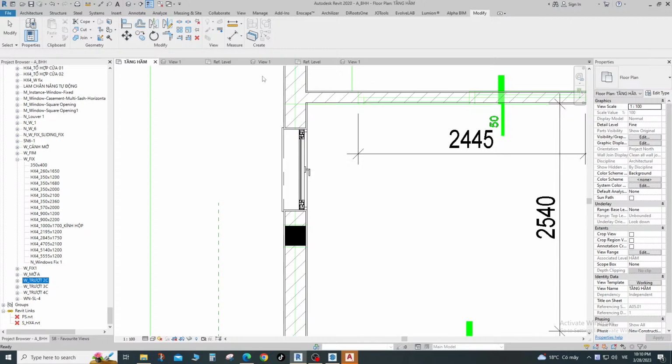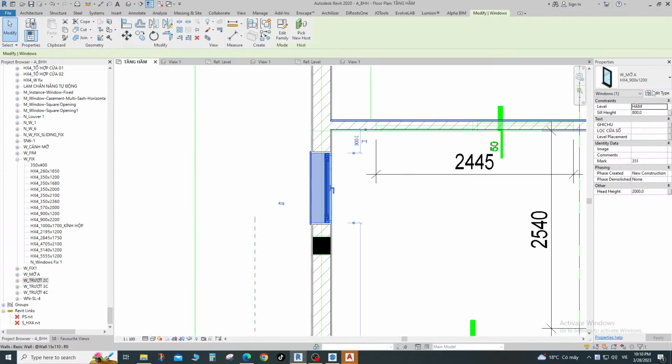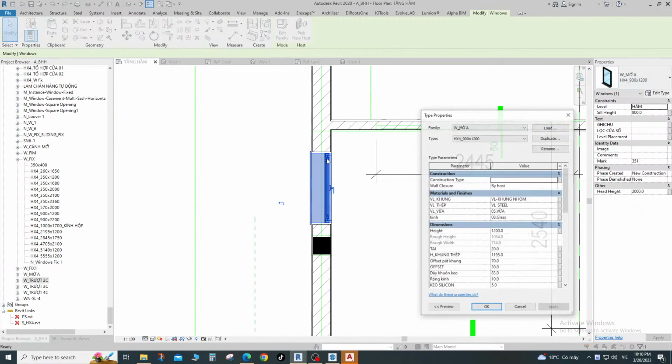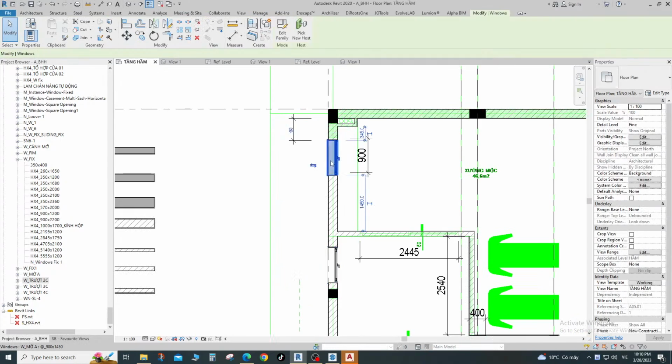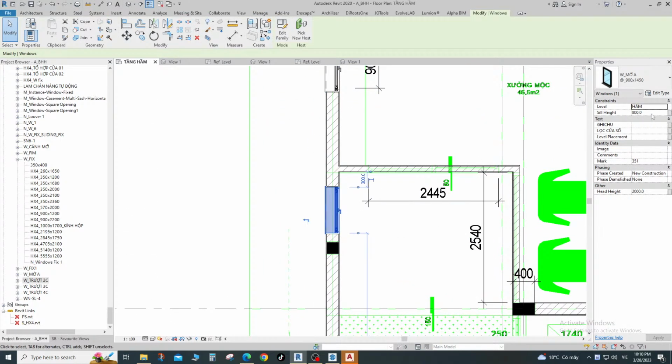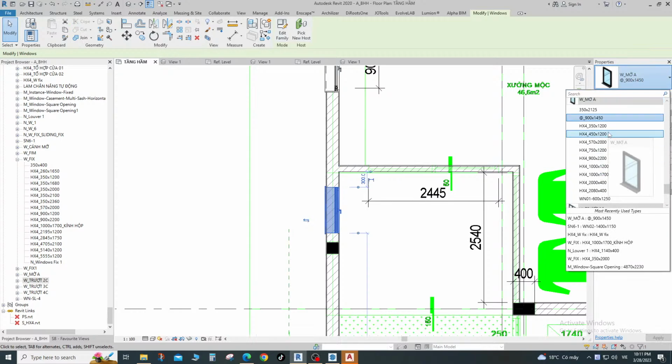You can see it's quite similar, so you can just use that, select all, and I'll change this to this. And for those railings following this floor, it's also very simple. You can just CS, create similar, and pick line. So pick the edge of this floor. So for example, I'll just pick, doesn't really matter, this one. So base level, you can change it directly to level 2, so that's fine. But you can also use pick host and pick new host and pick the floor.